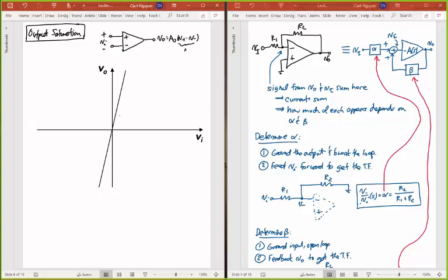That's VI. And so if I plot everything on this plot here, what happens is that this op-amp really has a supply rail, right? I'll call this L plus and L minus. I'm using L for limit. And so on this plot here, I could say this is my limit. Say that's L plus, and at the bottom, this is L minus. And this op-amp cannot put out any voltages greater than L plus and L minus. And so it all depends on how big your input signal is.